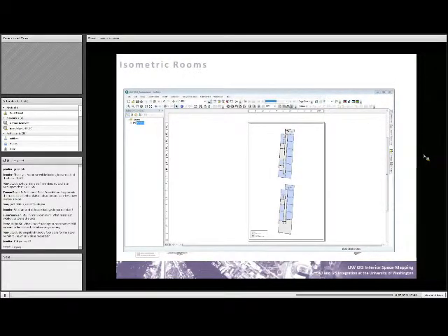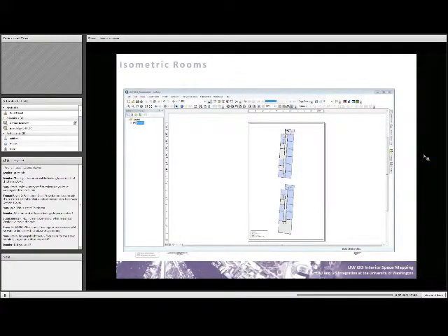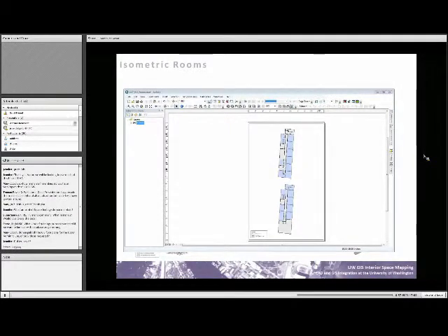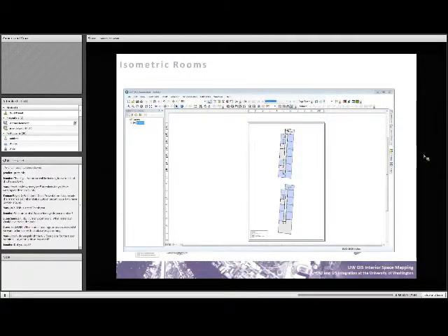Right now, we actually export the Revit file into 2D plan views, and then those just feed into our standardized CAD process. We have another set of custom code that will automatically convert the Revit standard into our standard. It's not very different. There's just a couple of little oddities of the way they do things versus the way we do things. So ultimately, it's not that hard, but it is adding an extra step in the process for us, and I'd like to remove that if possible.